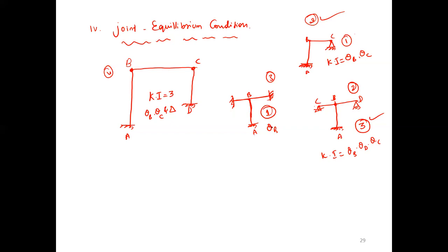Now tell me, what is the relationship for a portal frame between kinematic indeterminacy and joint equilibrium condition? Same, equal. Kinematic indeterminacy is equal to joint equilibrium condition. Same numbers.